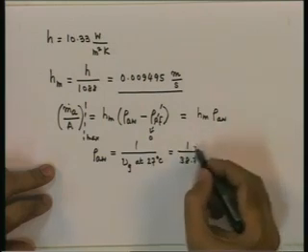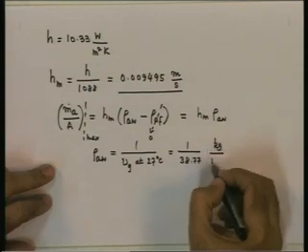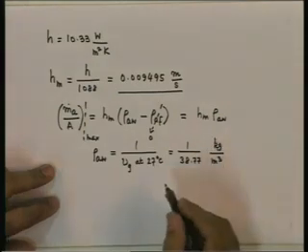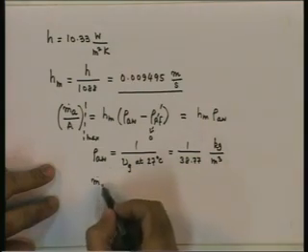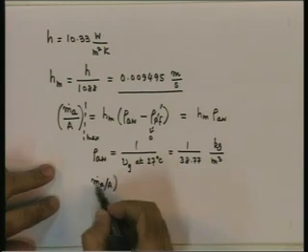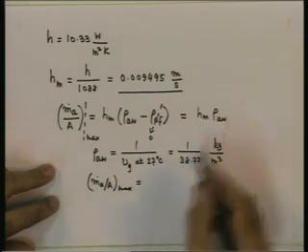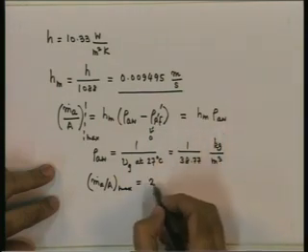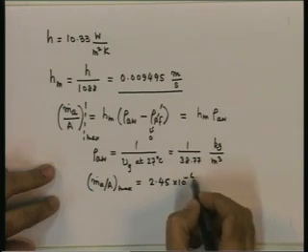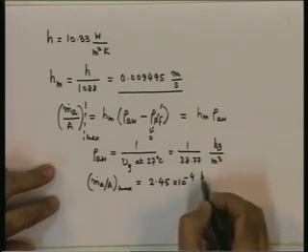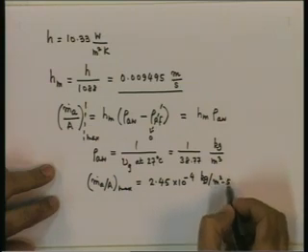So, rho AW will be 1 over 38.77 kg per meter cube. This gives us m dot A by A max to be Hm into rho AW, which turns out to be 2.45 into 10 raised to minus 4 kg per meter square second.